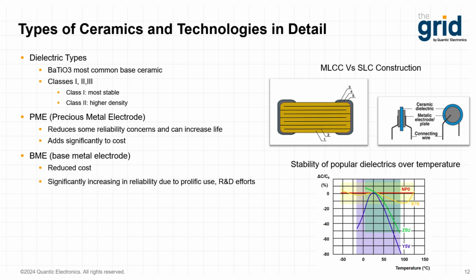And they can also be affected by things like electromagnetism, piezo effects from voltage surges, and other effects as well, such as temperature. Class 3 dielectrics have even lower stability and tolerances and are used for general purpose, lower cost applications. Other considerations within MLCCs would be the electrode type.